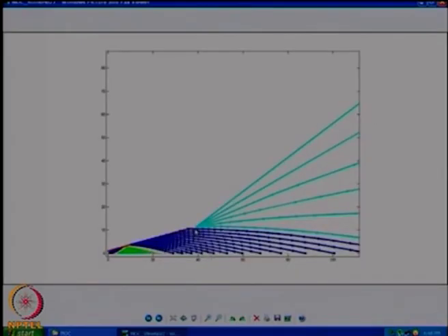I chose this point as exit even though my nozzle has stopped somewhere here. That is just cheap calculations. If you want more accurate, you have to use many more points here and get as close as possible to this value and then live with that value. I just did not bother. And after that, I gave an exit pressure boundary condition where the Mach number should have been 8, while the exit for this nozzle was supposed to be 4.